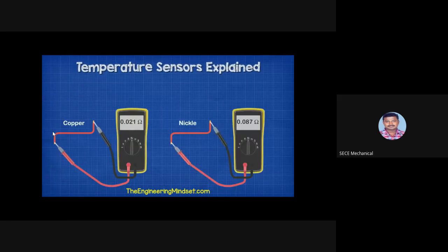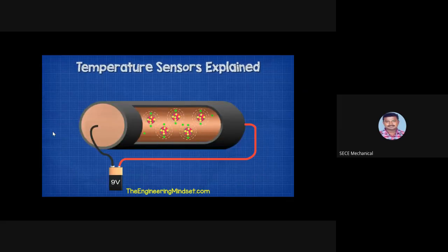Different materials have different resistance levels. The temperature of the material will change the resistance of the material. Most conductors will increase in resistance the hotter they get. That's very typical of metals. This occurs because as the atoms and molecules become excited, they move around a lot, so it's harder for the free electrons to get through without a collision.